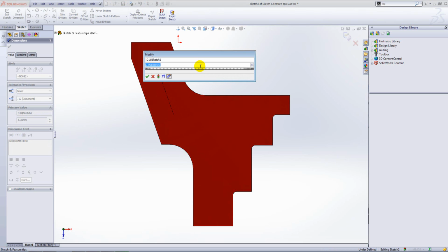metric. Also within the modify box, you have this scroll wheel here, which is set to increment up in increments of 10 on my machine. Now if you hold Control, you will multiply those increments by 10. If you hold Alt, you will divide those by 10.